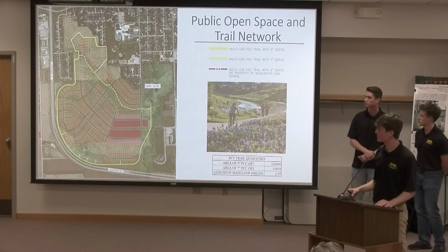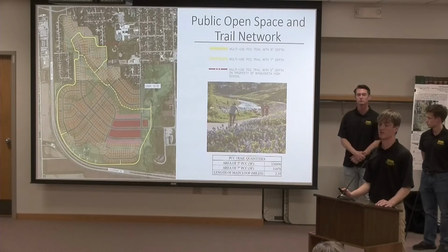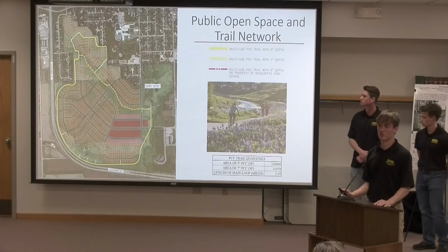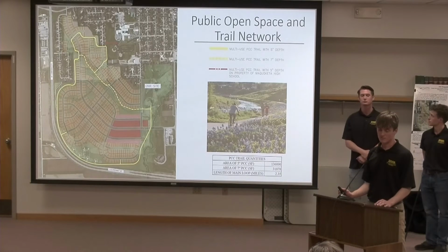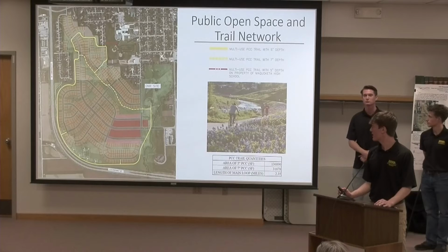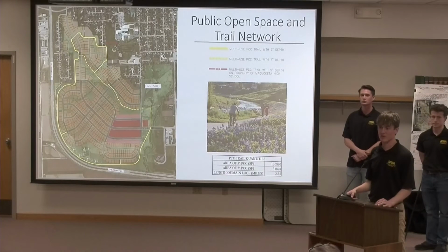Then moving into the trail design, we were able to design a trail based on the city's request for a bicycle and pedestrian multi-use trail. And so this trail is going to be 10 feet wide. It's going to have a depth of 5 inches of concrete, Portland cement concrete, except for the dash portion, which runs along the main drainage way there.